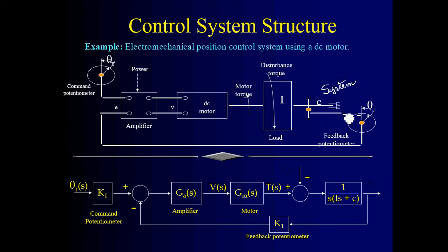And then you have this, which measures the speed, and what happens is a feedback potentiometer, meaning from this RPM, the omega that you have in here, right there, this omega is going to be converted into some voltage in here to compare here.